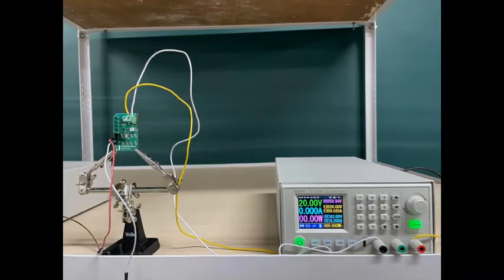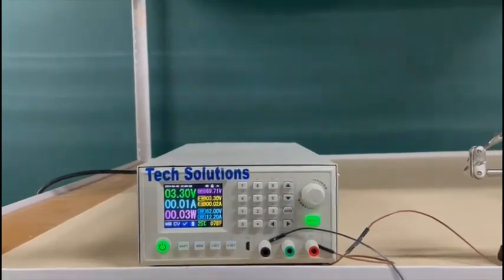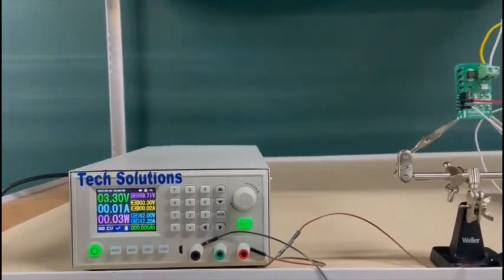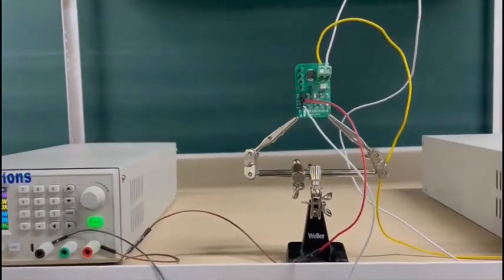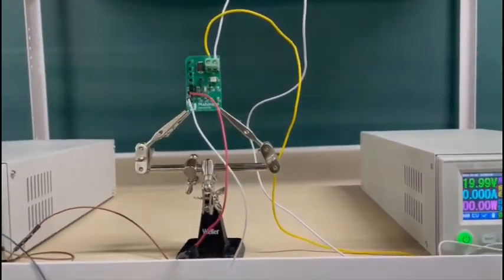The next step is to simulate a healthy panel. For this, a 20 volt input is connected to the detection circuitry, which emulates a healthy panel condition. The theory states that the detection circuitry is turned off when the panel is healthy. The turned off LED confirms the inactivity of the detection circuitry and hence draws no power when in this state.